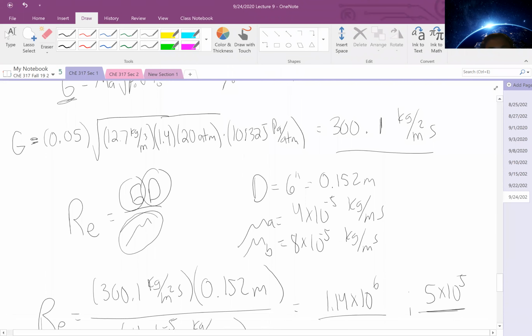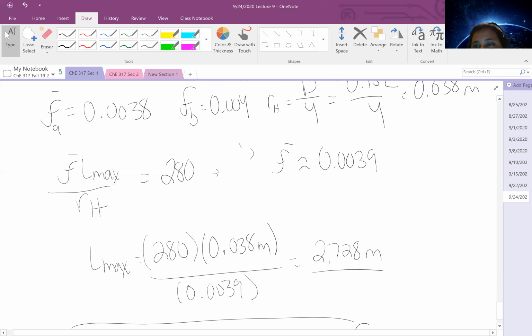And one of the things is, if you do a Reynolds calculation and you end up at essentially 4 times 10 to the 6th or higher, you can probably assume that your F is going to be constant. When you get to that high Reynolds number range, that's another one of those areas where you can make that assumption that F of A is F bar, and you can move on.